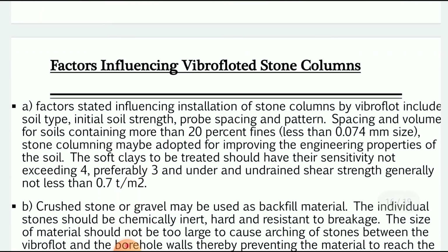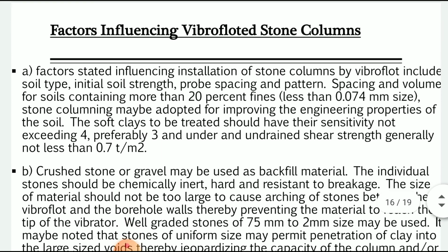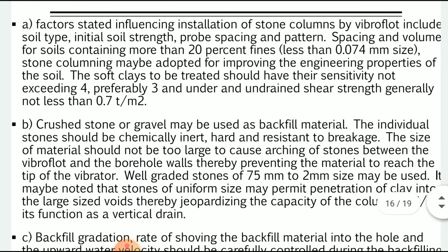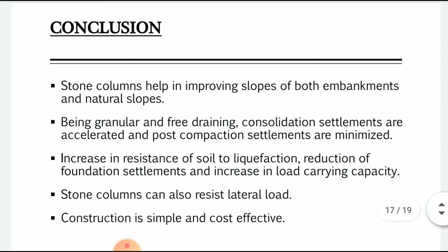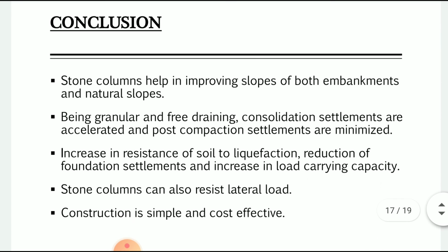Then these are the factors influencing vibro floated stone columns. Actually this portion is not present in your syllabus. Directly we will go to the conclusion of what we studied from this lecture: stone columns help in improving slopes, both embankment and natural slope. Being granular and free draining, consolidation settlements are accelerated and post-compaction settlements are minimized.